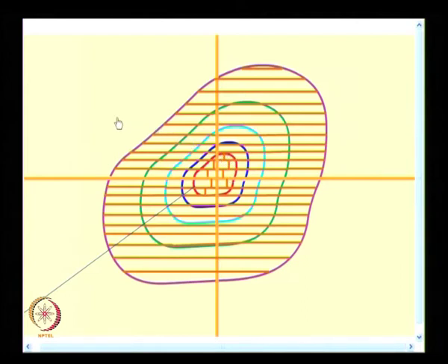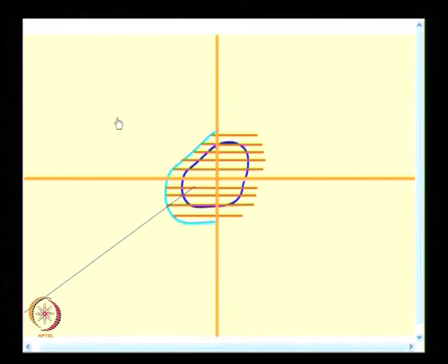So, the whole experiment is a little different in brittle coating. What I do is, I look at the structure for a given load, incrementally raise the load in stages. After raising the load, you stop it, hold it, go and look at the cracks, identify the ends of the crack, and then repeat the next stage, and so on and so forth. That is how you do the experiment.